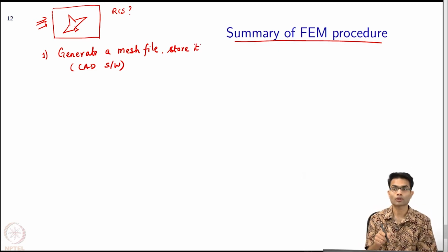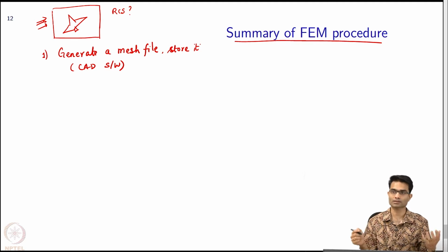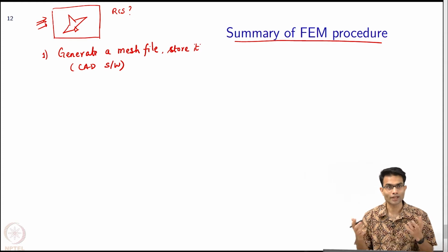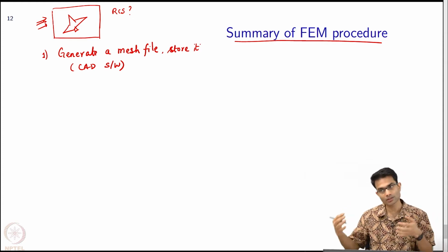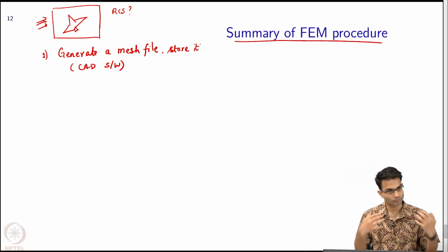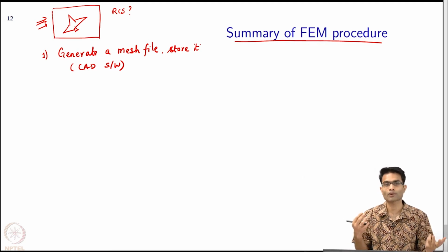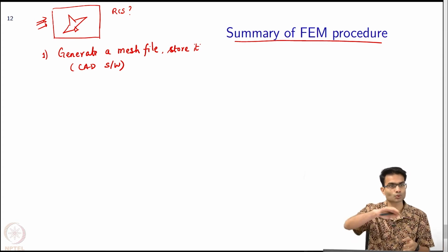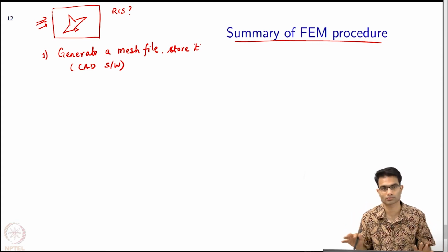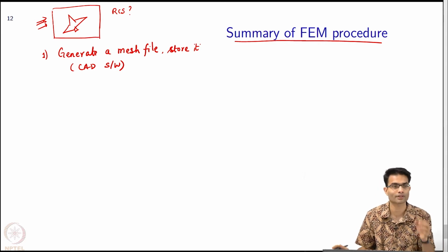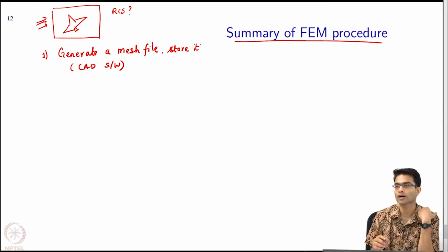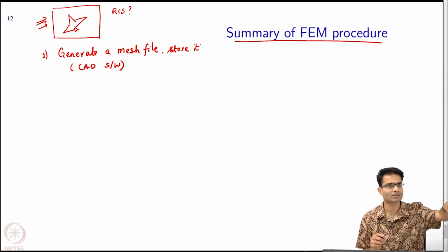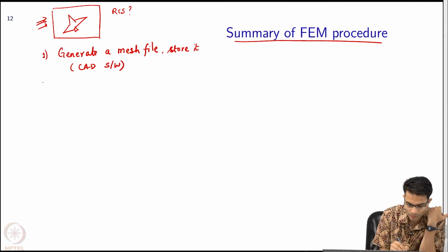For complicated objects, this is itself a big task. Imagine you are given, let's say, a MiG-21 or something. You need to have a realistic 3D model of this in the computer, and then you have to further fracture it. A real life object will have some very tiny things here and there which need not be meshed, so you should smooth over it. Meshing this is not a trivial thing by any means. Even CAD software is generally very sophisticated. Or you have some complicated electrical circuit, and maybe you don't want to discretize the resistor very finely. So, this is a complicated step.